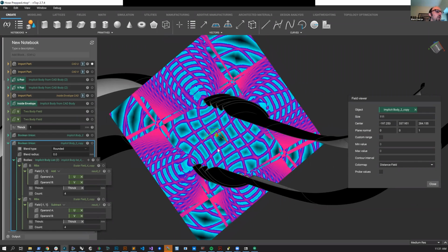The main points were that there's a lot more power in nTop if you're willing to go a little bit closer and look at the fields and look at their remote values. That in particular, adding and subtracting the fields gets useful very quickly, and the A minus B over A plus B field, AKA the two body field, is the opening gambit to almost every useful modeling operation in field synthesis and field design that I've come across. And that when you use these tools on imported CAD geometry, you can do absolutely amazing things with very little work up front in CAD.